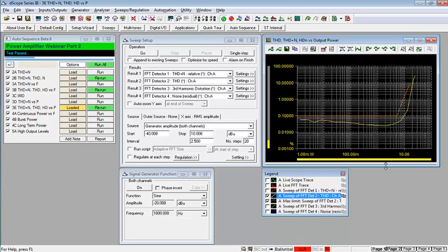So what we can do, and this might be a more appropriate test, is we can plot just simply THD, so total harmonic distortion without the noise, versus output power, and this perhaps gives us a slightly more realistic view of what's happening from the point of view of distortion in this particular device. And then if we wanted to, we could isolate the noise as a separate quantity, either in absolute or self-relative terms. So when we measure it in this way, as I've just shown you, we do indeed get a test pass. That's a relief. The amplifier isn't broken. It was really just a consequence of me misinterpreting the measurement that I had configured. So an important lesson there that hopefully I've made clear for you.